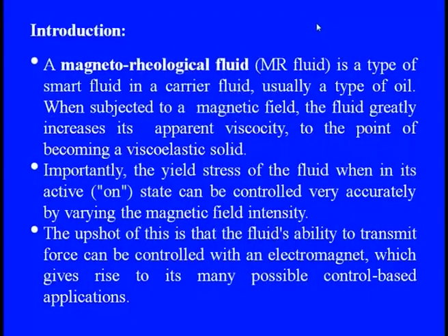In the magneto-rheological fluid, as the name itself says, we again have rheological particles, or rather the rheological properties of the particles, and a magnetic field is applied. So, it is a type of smart fluid in a carrier fluid, usually a non-conducting oil, and when it is subjected to the magnetic field, the fluid greatly increases its apparent viscosity, to the point that it becomes a viscoelastic solid.